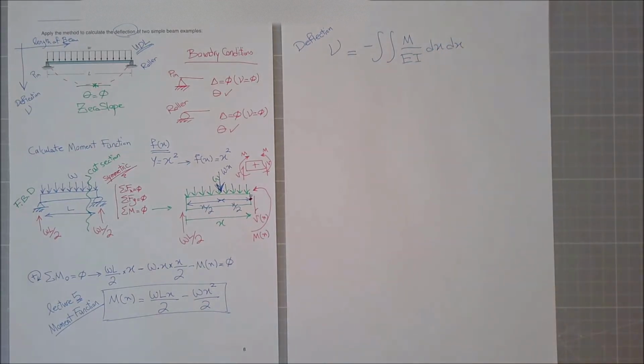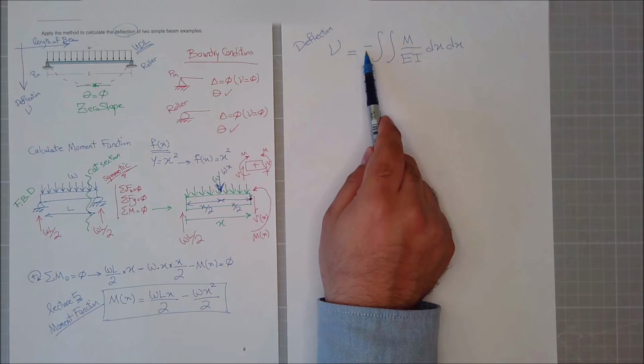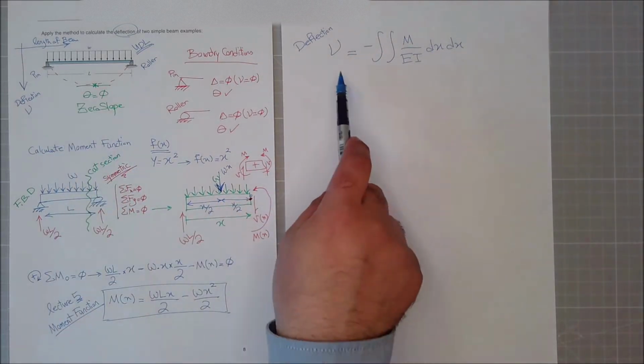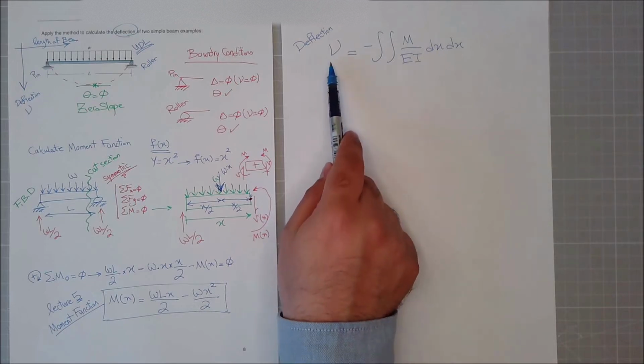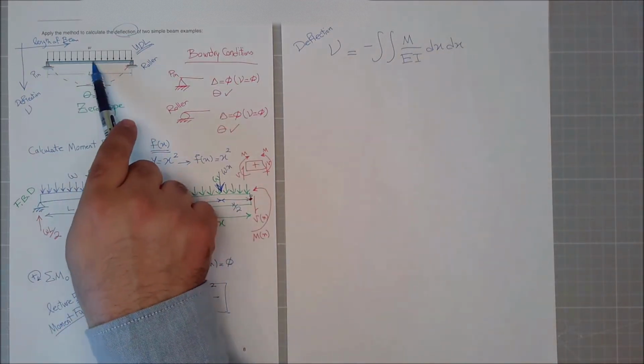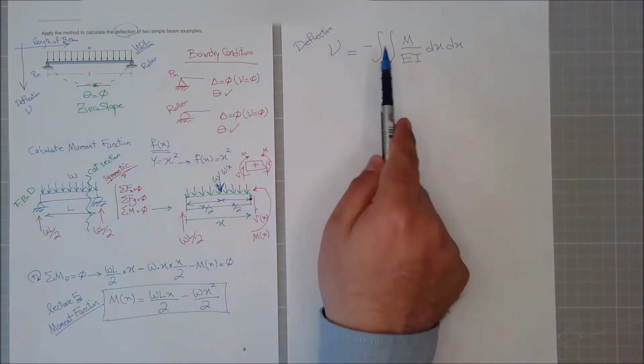Yeah, we proved it through the elastic beam theory. And we put this negative because if we get a positive value of this deflection, we know that the positive value means that deflection is downward. That's why this negative exists over there.